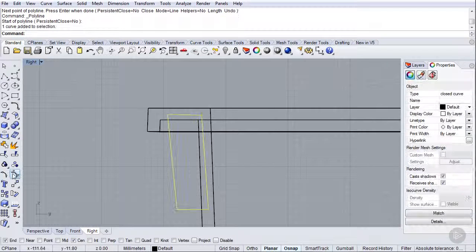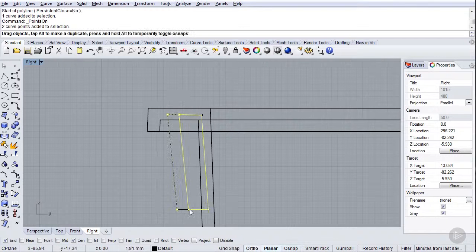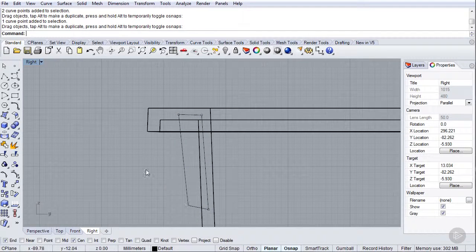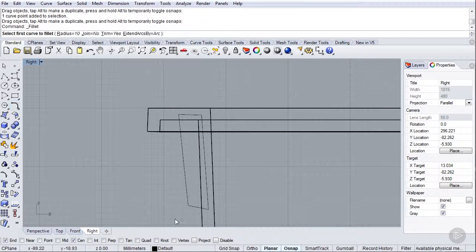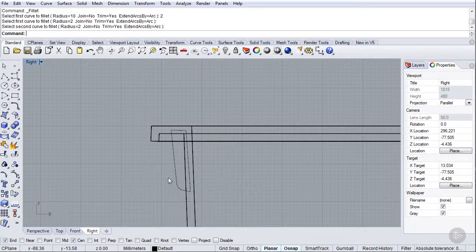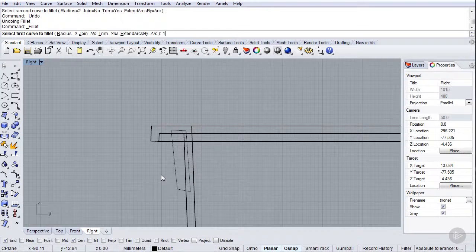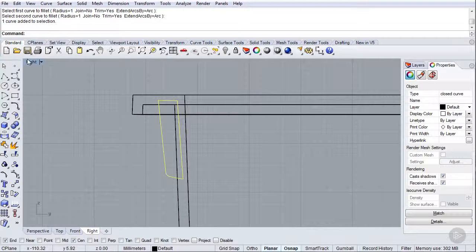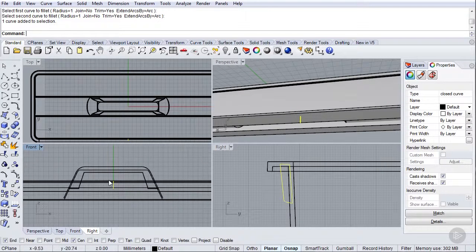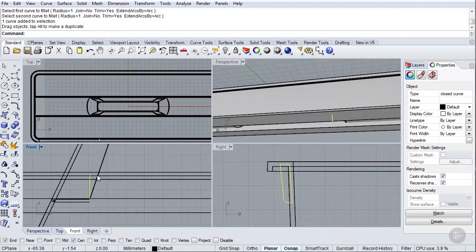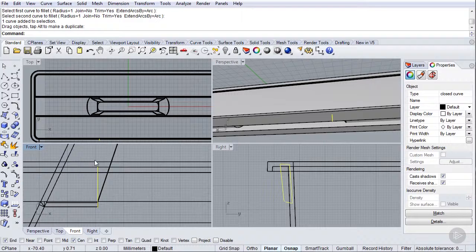So just drawing some curves, I'm going to pick the edit points, move them in a little bit more, angle this up just a touch. Put a small radius on this bottom edge here. It's too big. Right click to repeat. 1 on the keyboard. And they are around about in line with this hole we've made.